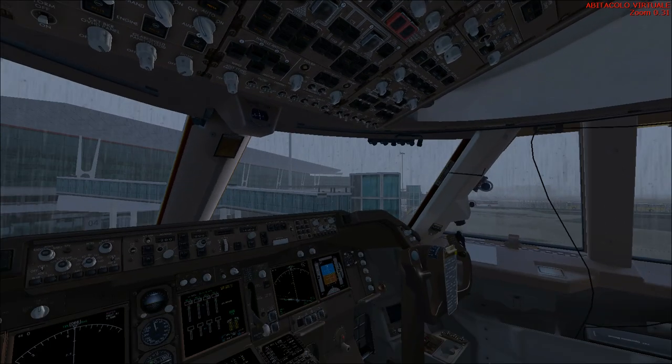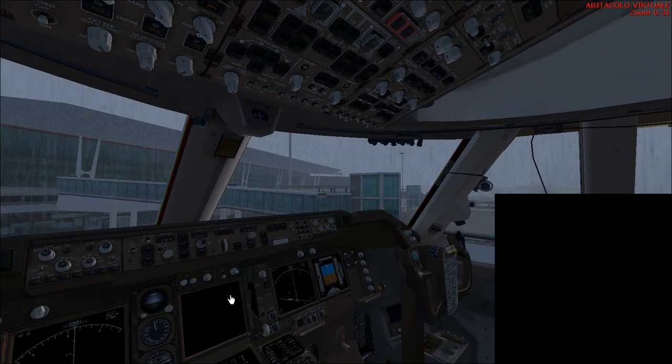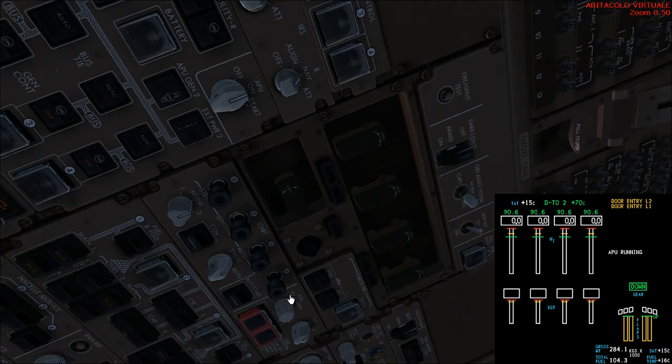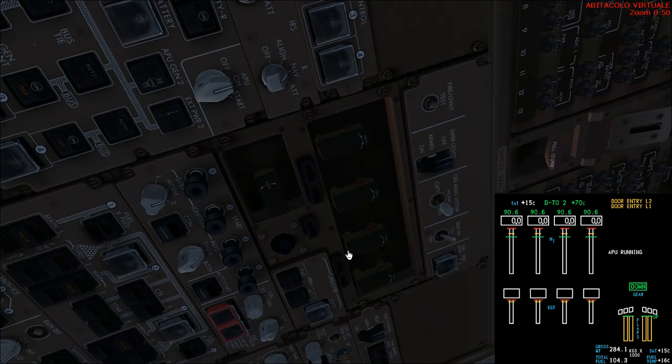If we go to the main panel and select the upper DU, you will see the fire override testing. You will see the red lights coming on, with a red indication that the fire override test is in progress, and when the test is passed, all the lights will be out, and a red light with fire test passed will be indicated on the upper DU.